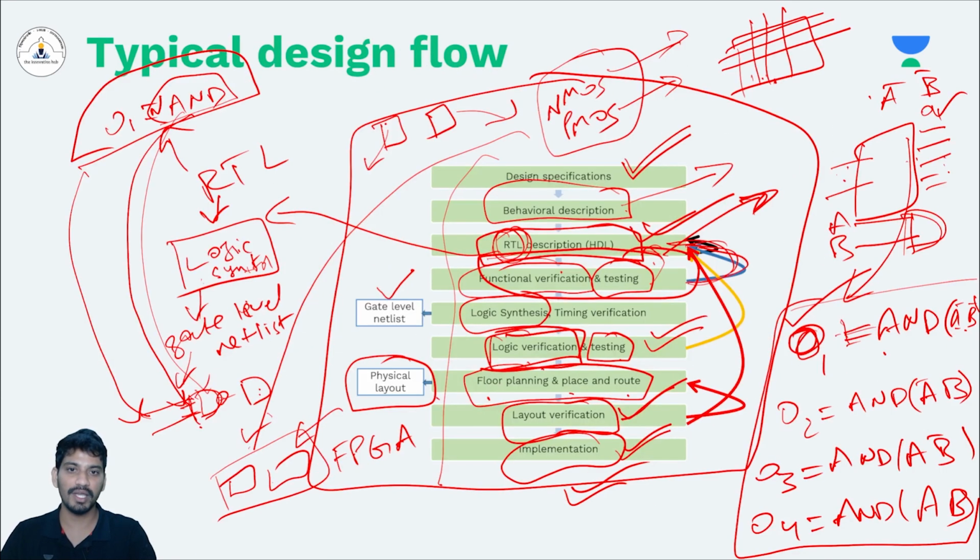In the case of ASIC design or circuit design, you don't have this feature because you need to connect the circuit first, and then after connecting the entire circuit, you have to verify whether the circuit is working properly or not. But in the case of RTL, you just write the code and then simply tweak the inputs so that you can optimize in the beginning stage of the design itself.